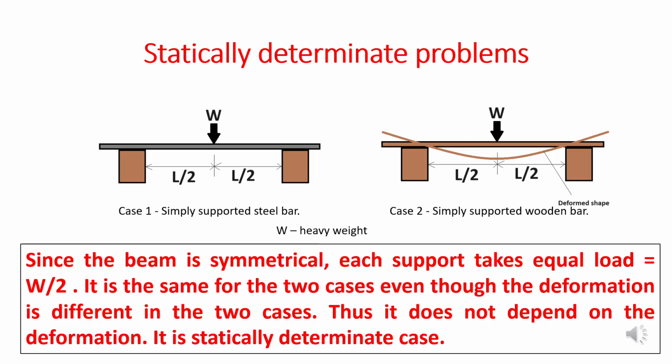So this much is clear, right? These are statically determinate loads because these do not depend upon the deformation of the structure. They are independent of the deformation of the structure. As long as the load is the same, they'll give the same reaction.